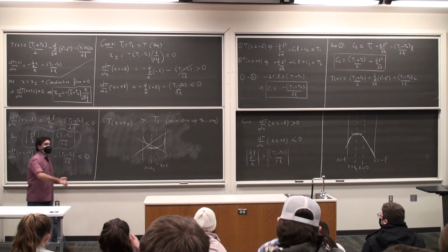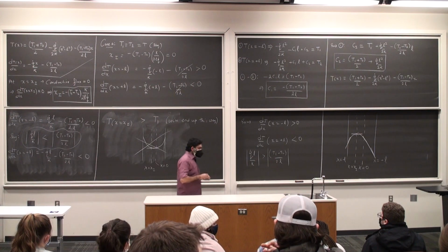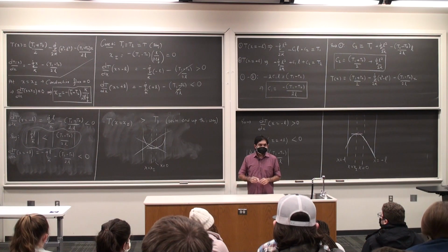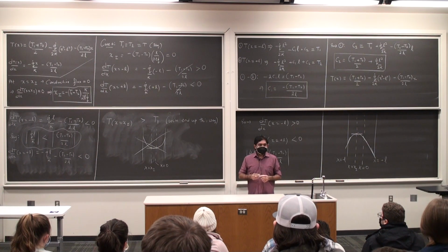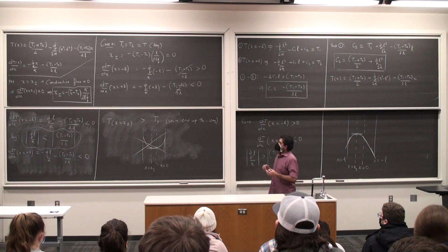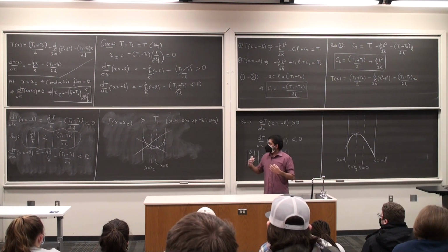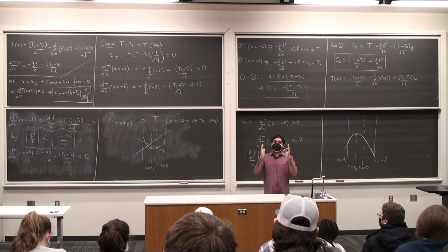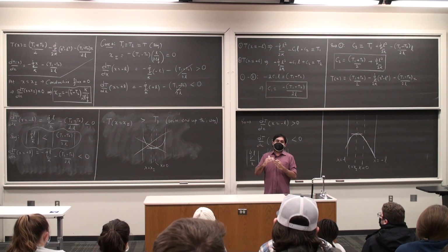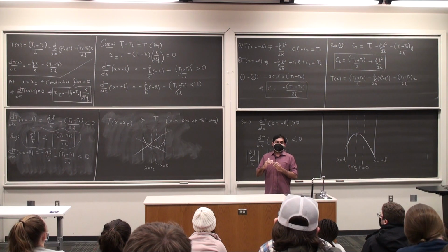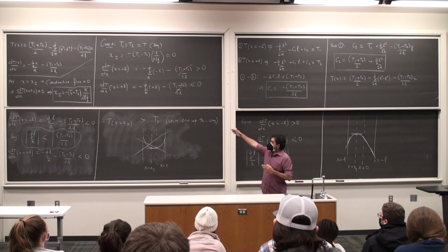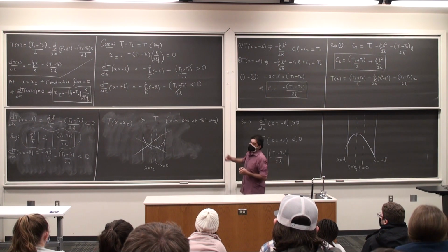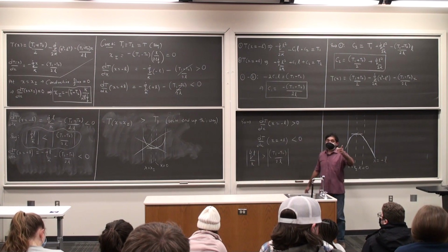Yes, sir. Could you maybe explain how we could intuitively look at that and know why it's that and not that? Or do we have to go through the math? You could intuitively look at it. If you have heat coming in through both sides, then the temperatures at the edges must be greater than the temperature at the x equal to xi location. But of course, you have to go through the math to figure out what T1 is, T at xi is, and then you'll see that, okay, that cannot happen. Thank you. And that's for positive heat generation.